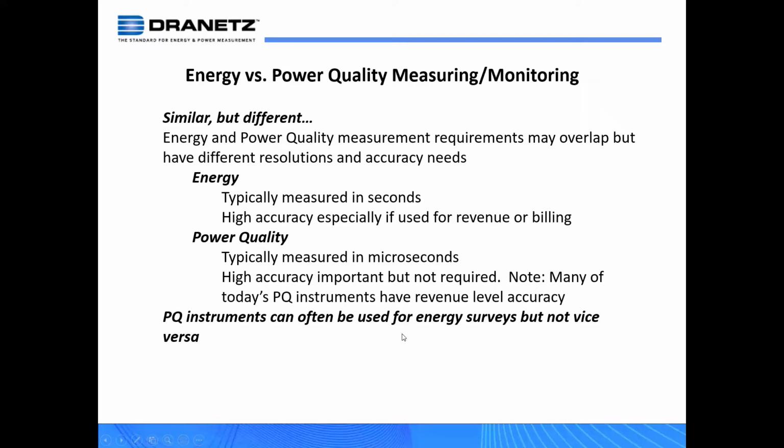So you can use power quality instruments, if designed from the ground up for power quality applications where your resolution is in microseconds, in both applications. I can use them for PQ applications. I can also use them in energy management applications, but I can't vice versa. So that's the important thing to remember.